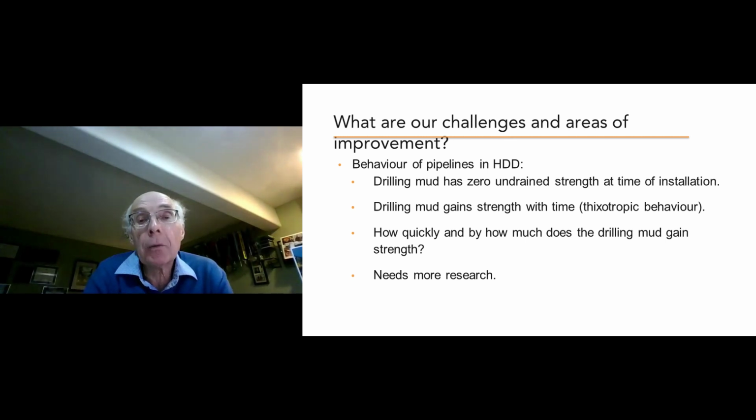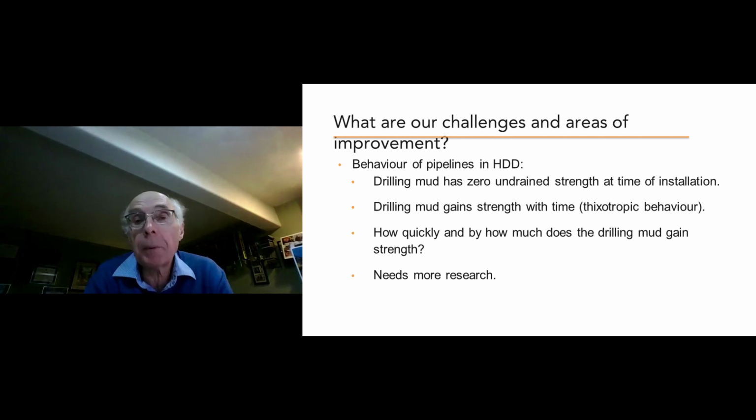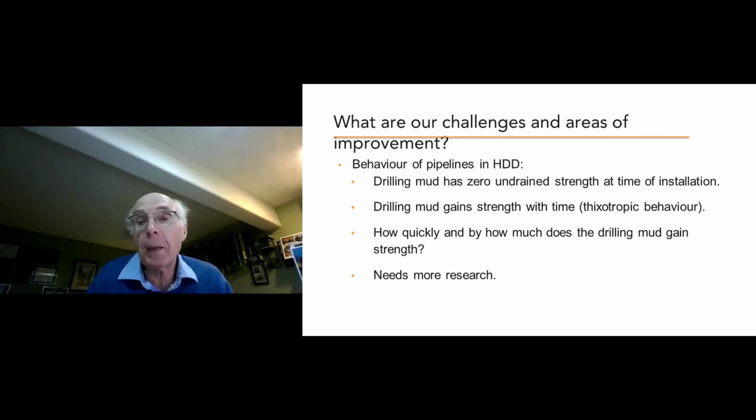We also know that, being thixotropic, the drilling mud will gain strength with time. There are chemical changes that occur in the mud. Water is absorbed into the surrounding soils, and so all of that will change the strength of the drilling mud. But the question for us is, how quickly and how much does that drilling mud gain strength? And it's an area that needs more research.